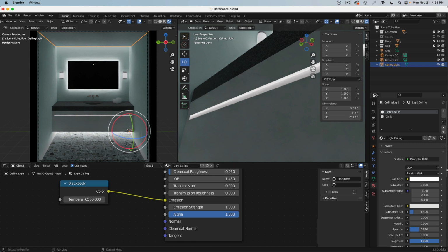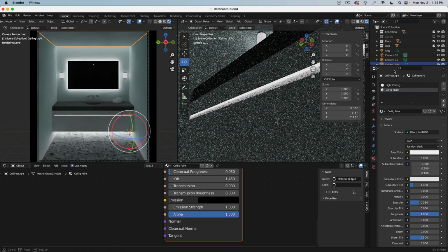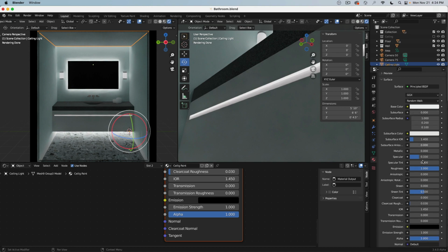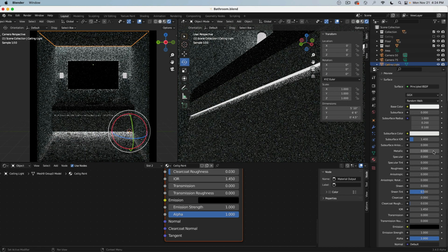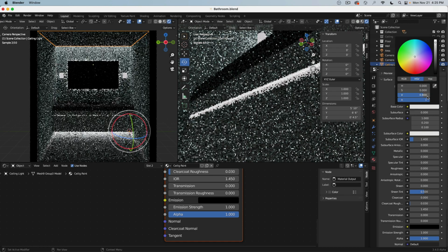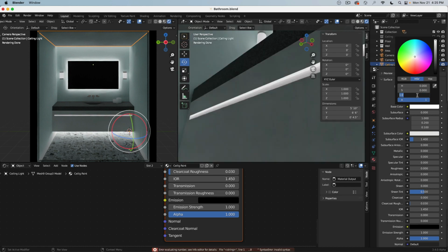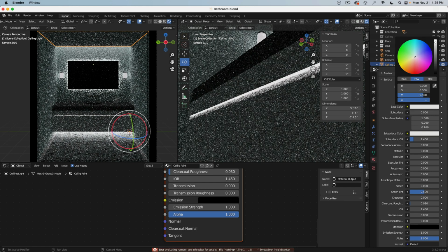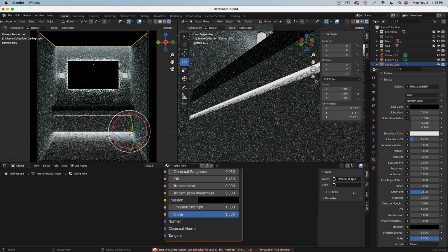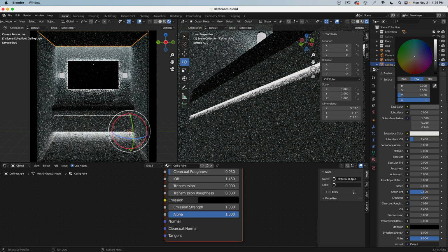We can start with the ceiling again. So here, ceiling there, let's say ceiling paint. Okay. Most of the stuff we can also do in this element here. So let's make this a matte material. And 0.8, it's kind of like a really bright white. Do not make this 1 because we don't have a white that is that perfectly bright. 0.8 is kind of okay. The same like with black. This is like a black hole. Darks are more dark, but not really black.